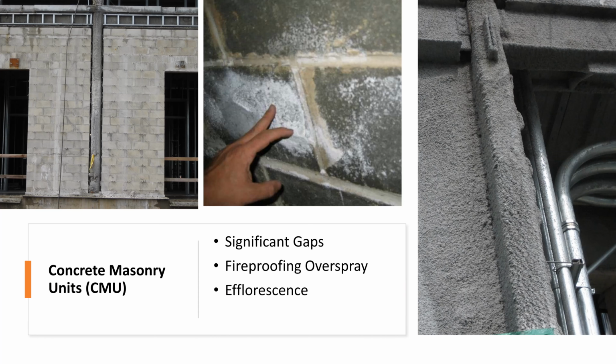So concrete masonry unit gets wet. As it begins to dry, it starts to pull the minerals and salt to the surface. So if you start seeing this white stuff on the wall, it's an indication that there was at some point quite a bit of moisture. And number two, the fact that it does have to be cleaned off. It's kind of like salt just on the top. If we try to put a membrane on that, it's not going to stick well, right? So this is a case where I go, hey, we can't install on the substrate without removing some of that efflorescence.